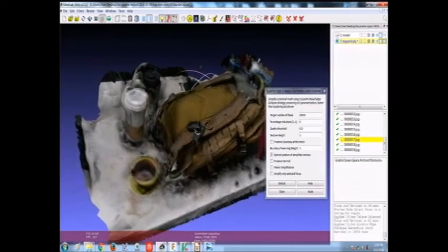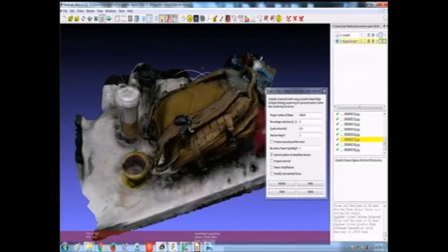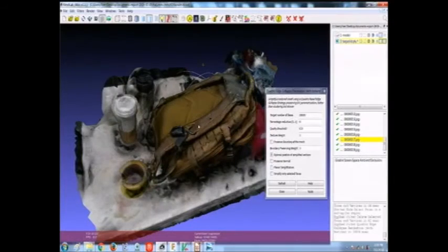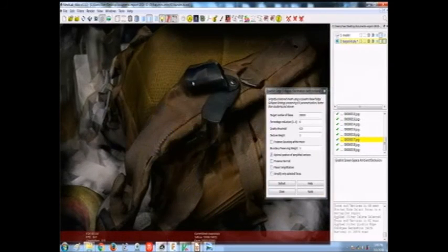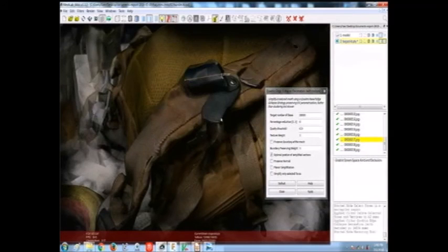If you ever have a known distance on your image, because, reminder, photogrammetry is a naturally dimensionless method of reconstruction, like if we know that this buckle right here is 40 millimeters or something, we can just do the comparison. Right now it's saying it's 0.27 units, and we just do a quick little conversion, apply a scaling factor, and then it's dimensionally accurate. So things are pretty much that simple.